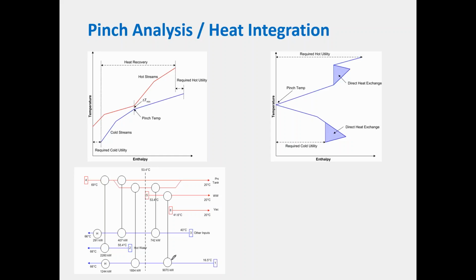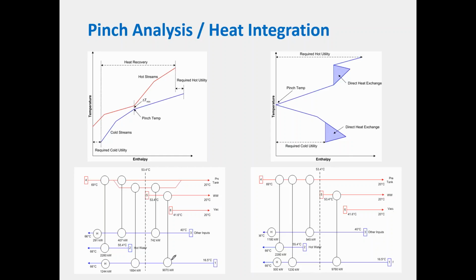And then from that as a basis, once we've established those targets, we can look at what our current heat exchanger network may look like. There are some techniques to look at which individual heat exchangers are the most likely candidates for change, or increasing the utility use unnecessarily. There are some formal methods around that, which is the wider pinch analysis technique.